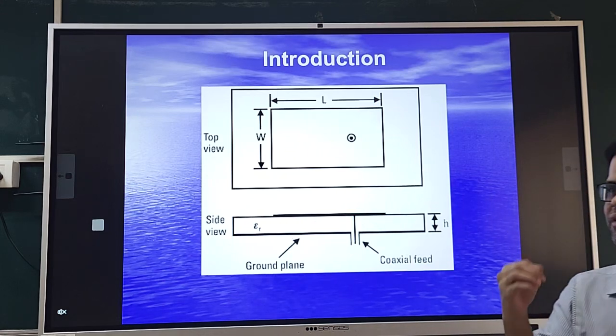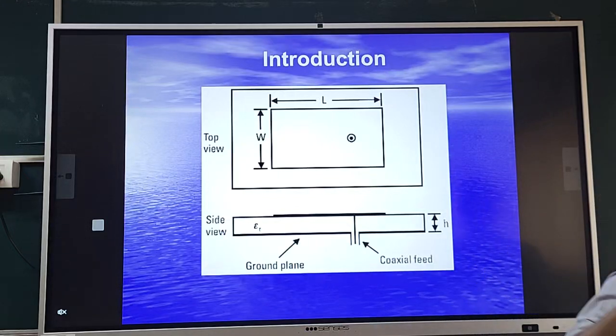How? Again, that we will see more in the broadband microstrip antenna design phase. So that improves the reliability of the microstrip antenna against substrate parameter variation. This is a very important design aspect. So we have touched upon the different features one should look out for in substrate selection. In the lab, maximally we use FR4 because, as I mentioned, RT Duroid is very costly.